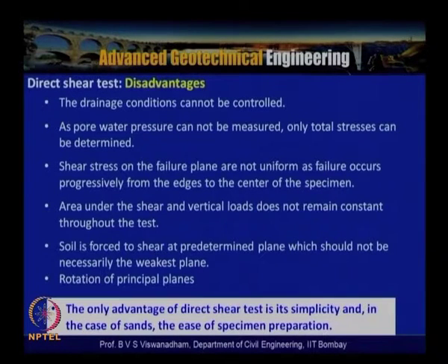what can be done is that when you have a shear box, and if you want to get, to some extent, consolidated and drained parameters, the sample can be prepared, particularly if you are having some silty sand or silt samples. The samples can be prepared either under remolded conditions or undisturbed conditions, and allowed to saturate under a particular normal stress over a period of time.